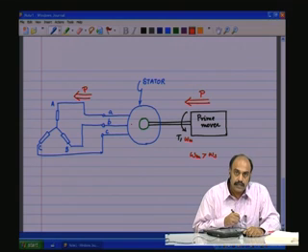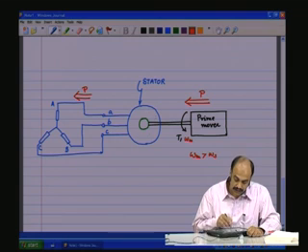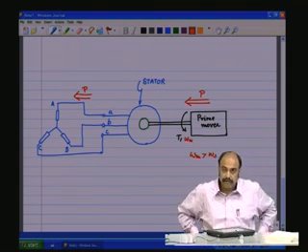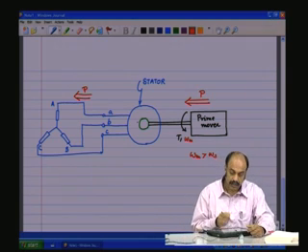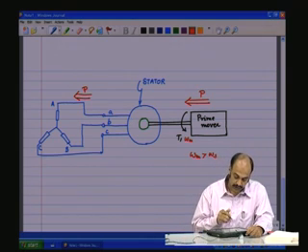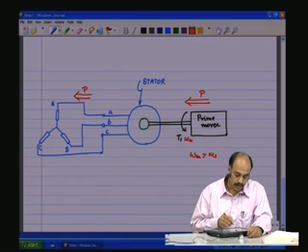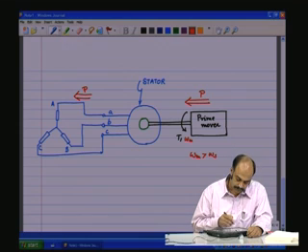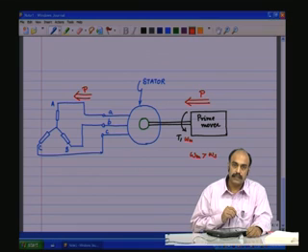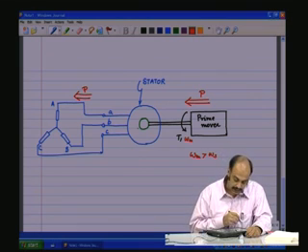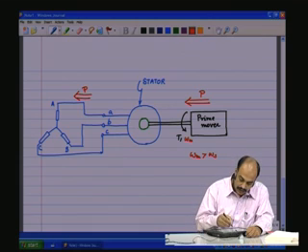Now, how is the reactive energy generated to maintain the field in the machine? So we can't have an induction motor just like this in this manner, because there is no component here which is supplying the reactive energy. So therefore, we put a component which supplies the reactive energy to the machine to maintain the rotating magnetic field within the induction machine or the induction motor.